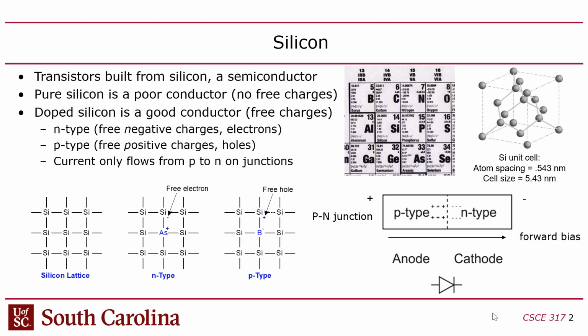So this is called a forward bias, where you've got a positive voltage on P relative to the N, and therefore you're trying to send current from P to N. The reason that works is because the majority charge carriers inside the P, and these are the holes, the holes get attracted to the junction between these two, right? And likewise, the majority charge carriers of the N-type, the electrons, they get attracted.